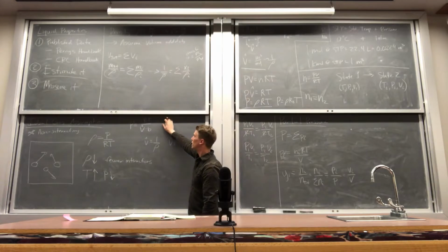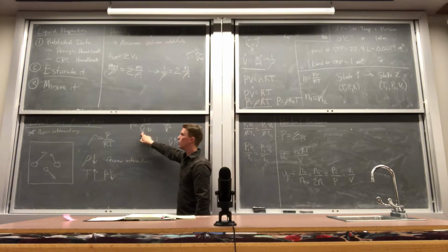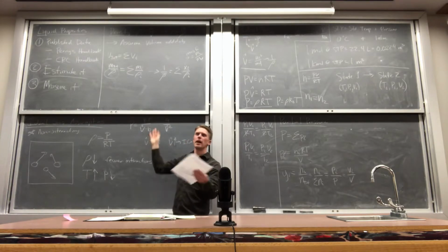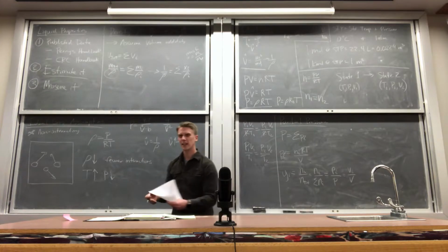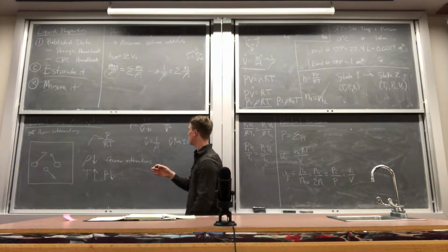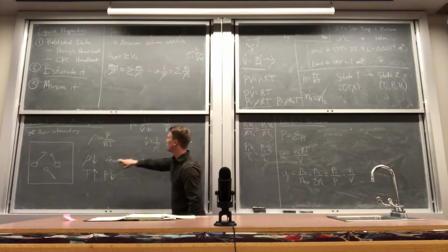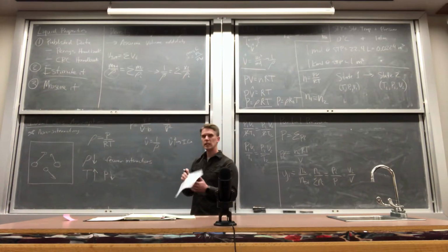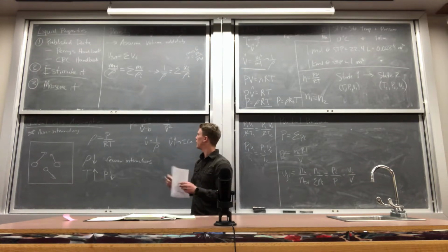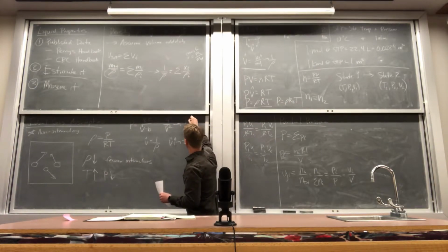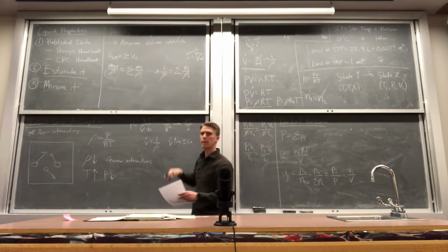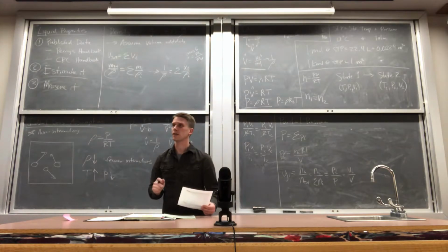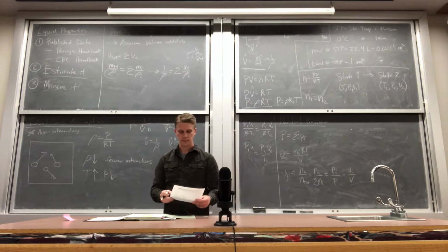It goes to 0. As our specific volume goes up, what happens to this minus b term? It just becomes insignificant, right? Like it's 1,000,000 minus 1. Yes, it's not technically 1,000,000, but it's pretty close to 1,000,000. So we can see that as your density goes down, your specific volume goes up, all of these really fancy complex equations simplify down to RT over v. Right? And then we get our ideal gas law behavior back and reestablished.